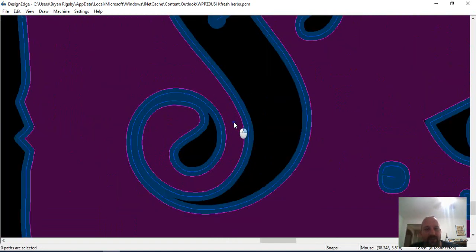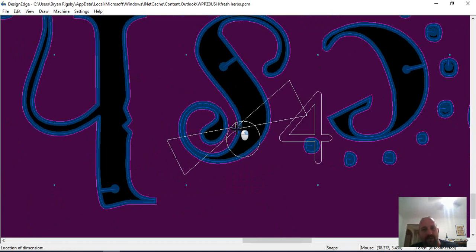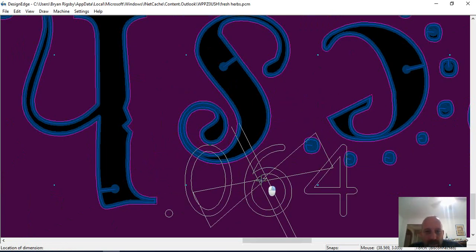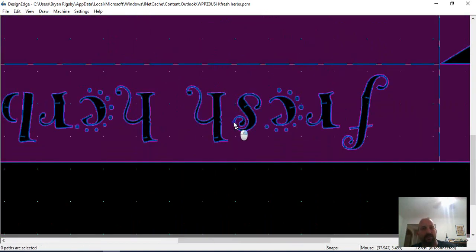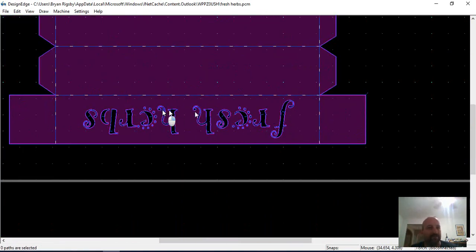So if you're cutting with fine cuts, you're probably okay. But that's only 60 thousandths wide. So if your kerf is not set right, that little S is going to burn up and fall off. But 60 thousandths is enough to hold if you have everything set right.